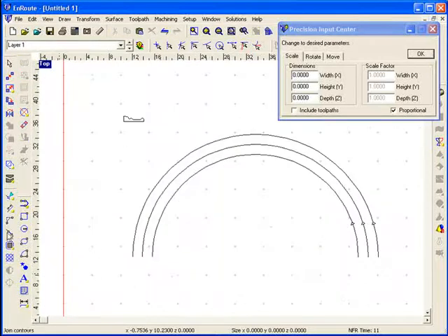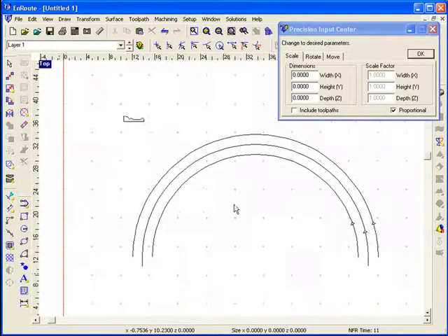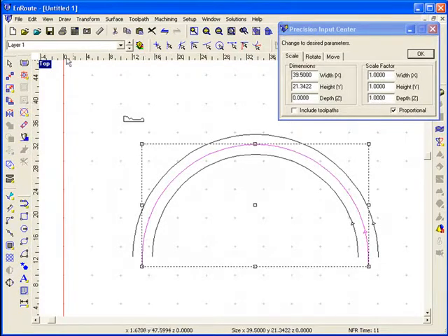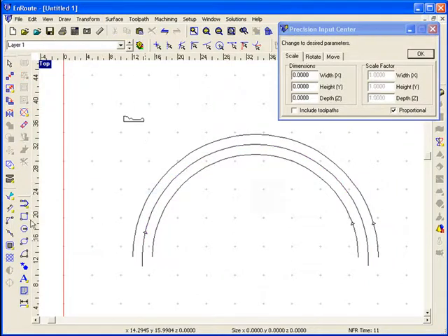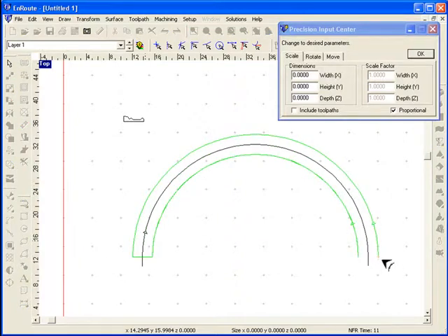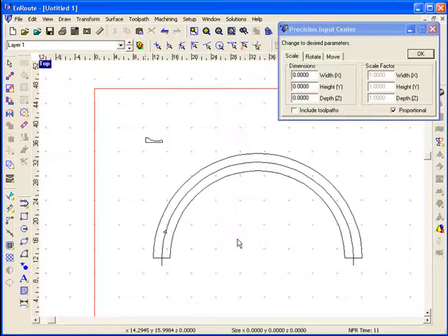Now I'm going to extend the middle lines a little bit past the edges using the extend tool, and because when it comes time to setting this profile around, I want the outer edge of this part to be on the outside, I'm going to select my middle profile here and reverse the direction. Now using the join tool, I'm going to close the shape I was creating, and the join tool selects one open edge and allows you to close it to another open contour, joining them together.